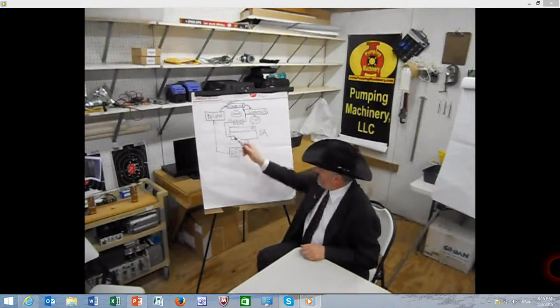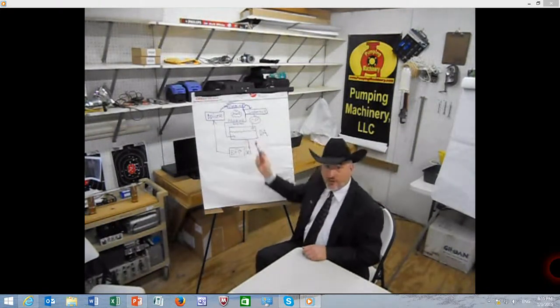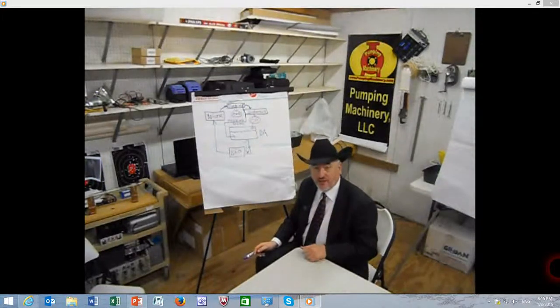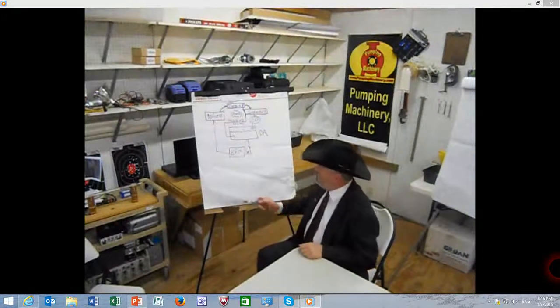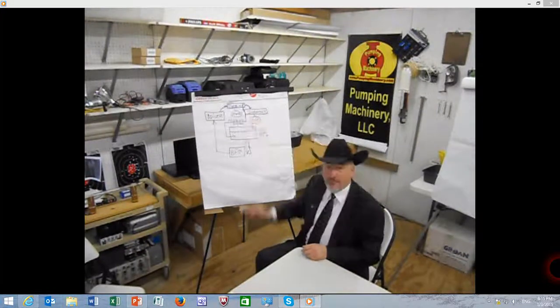The DA is usually roughly two-thirds full or so. It's mostly liquid water with a small steam fraction. Usually it's right at saturation or a couple of degrees above saturation, in a subcooled region. So everything is going nice and smooth, I think, until something happens.